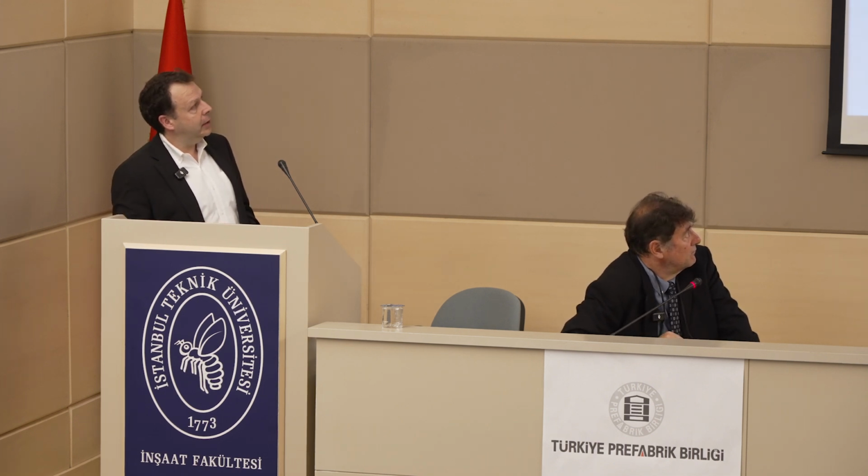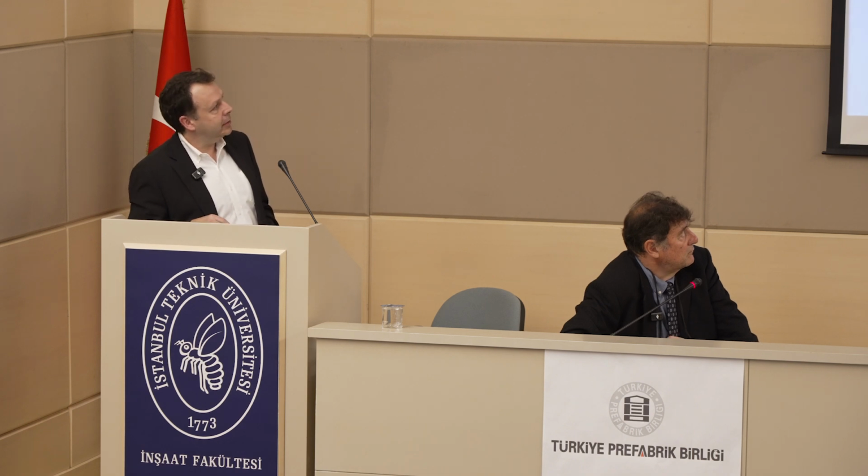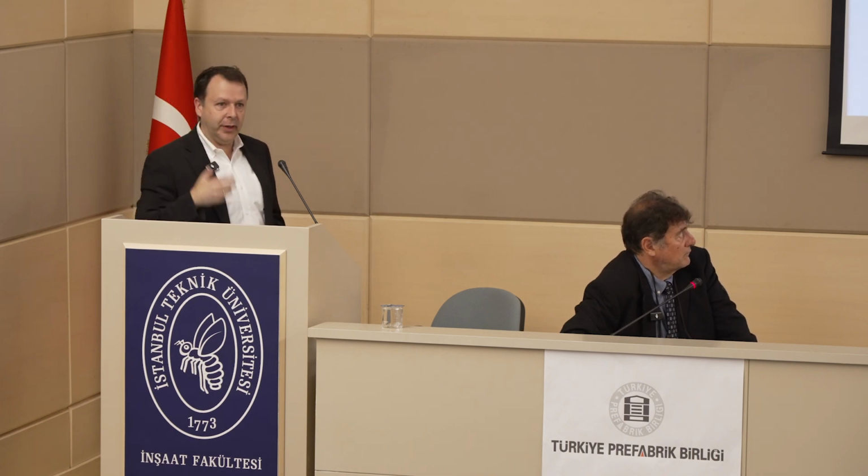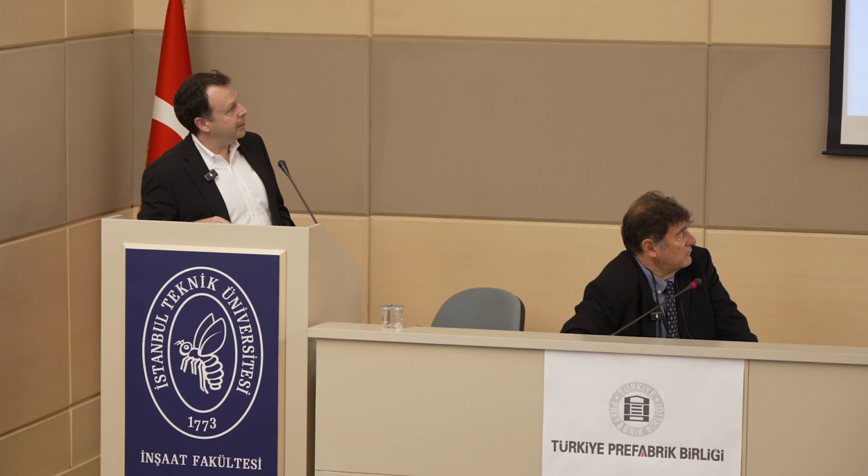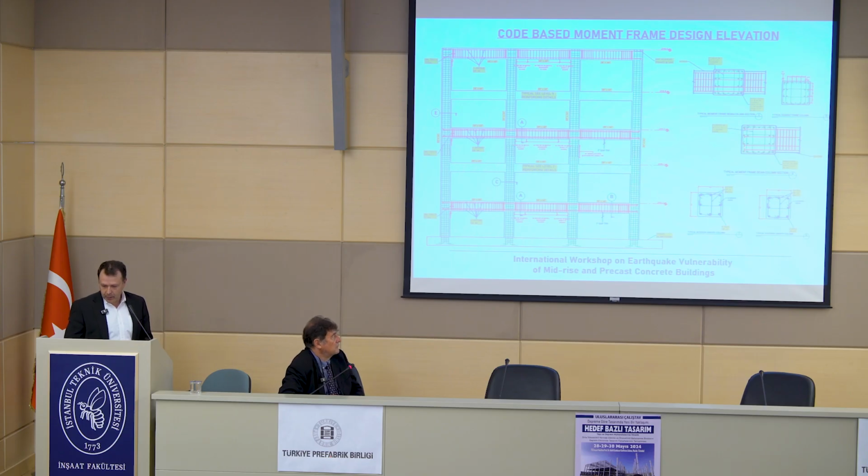And as part of the design process, detailing, an initial detailing of the beam column joint goes a long way to avoid a lot of iterations later. So early, even in the preliminary design, start developing these sketches so that really you get a full perspective of can it actually be buildable. And at the bottom there, this is the columns that are part of the moment resisting frame, and these are the gravity columns.